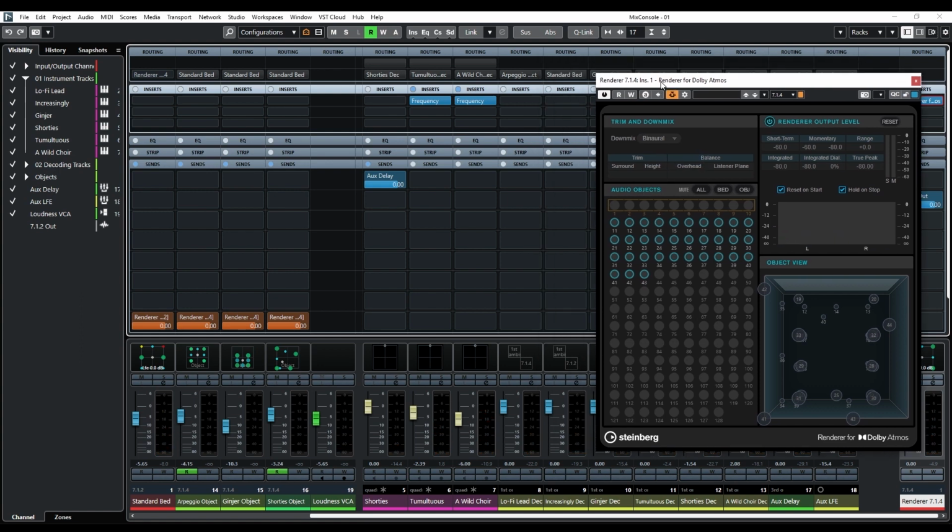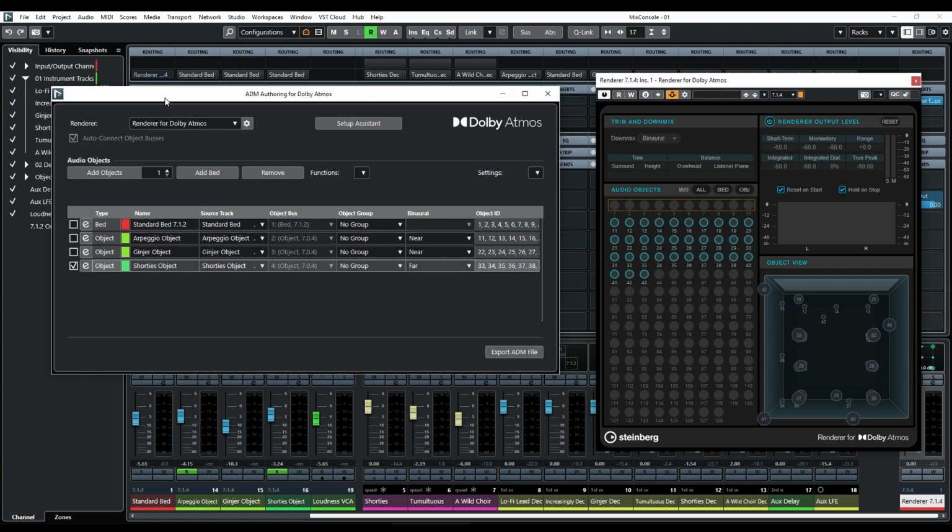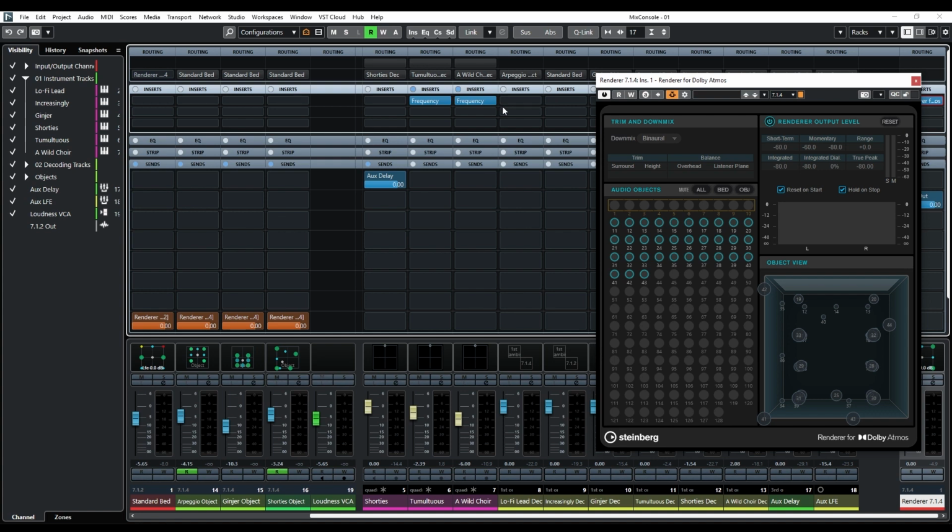And finally, we have our binaural mix. Our binaural mix is similar to the stereo mix, but it contains extra metadata, which is where your objects are going to be binaurally. They can be near, they can be mid, or they can be far from the listener. And the way you do that is you go to the ADM, and here is where you choose each of your objects and how they behave when they sound binaurally. So I have set my arpeggio object to be near, my Ginjer object to be near, and my Shorties to be far. So binaurally, it sounds like this.